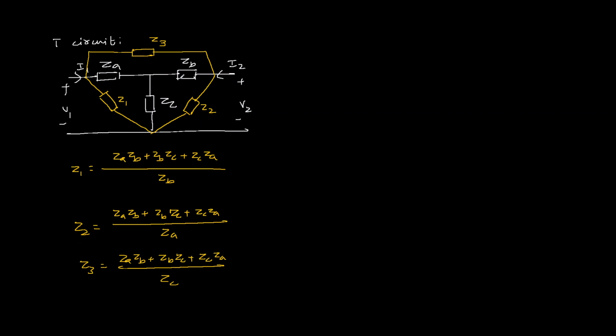So we can redraw this circuit, which is now, after converting from star to delta, the circuit becomes pi network or pi circuit.